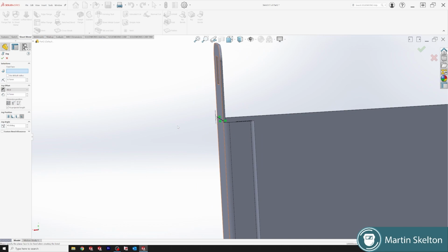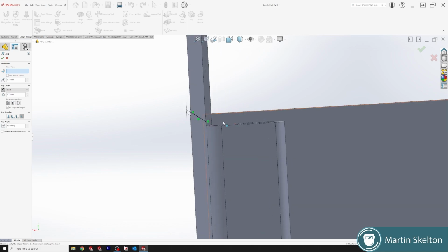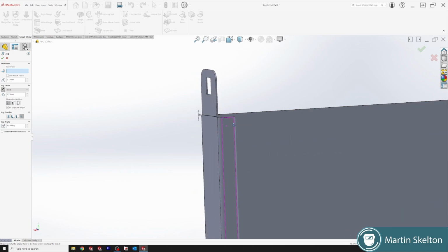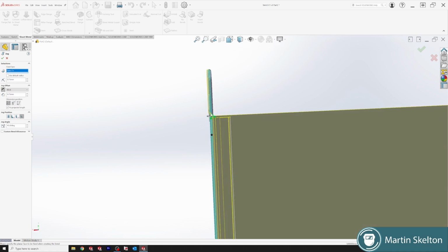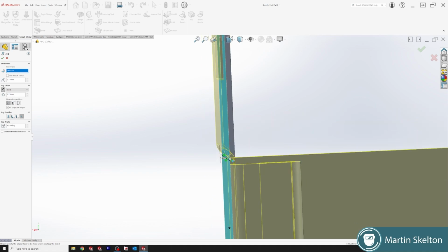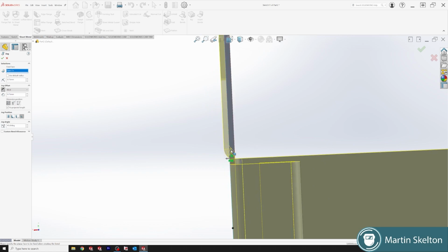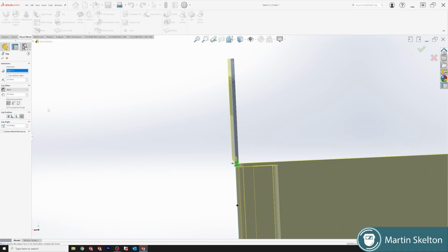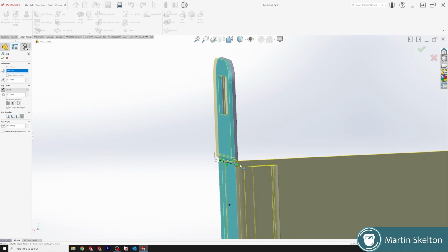So this is probably a custom tool that would do something like this because you have to really push the jog to work. If it wasn't a custom tool, you'd have to leave it all at the same angle and radius because you don't want to be changing your V-dies, etc. But you could get a custom tool probably just to press this small jog in one. Obviously for something like cable tray, it would be a CNC process that would push out these, or at least finish the ends of them.